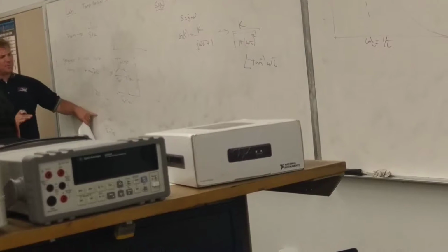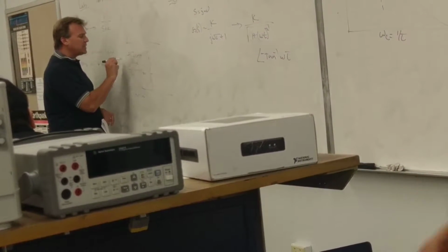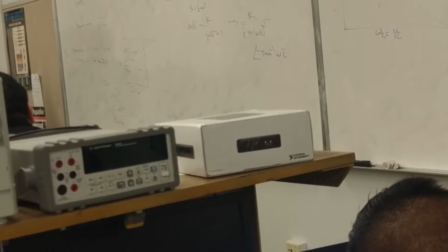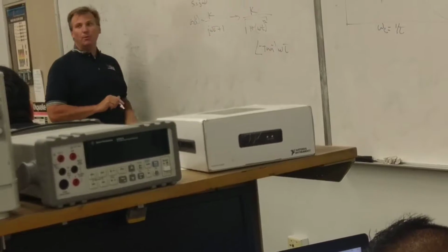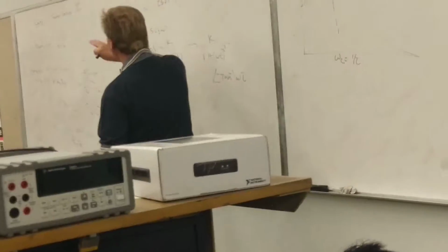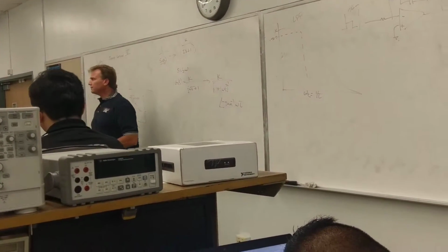So you're going to use this percent duty cycle. You're going to generate a PWM signal of some period T that I tell you guys, to be able to control. You're going to control T from LabVIEW on a VI, and you're also going to control the duty cycle using a dial on LabVIEW.